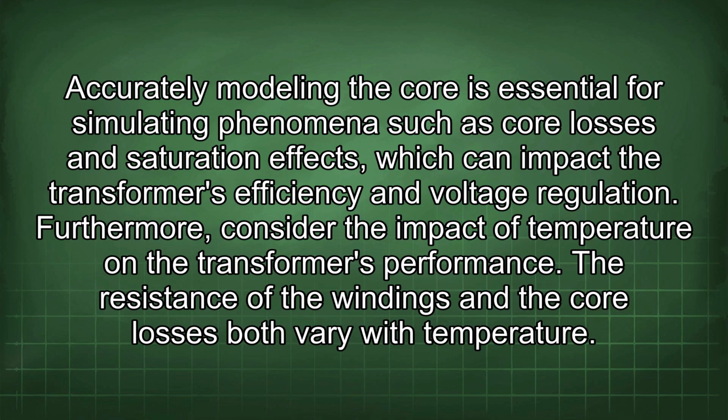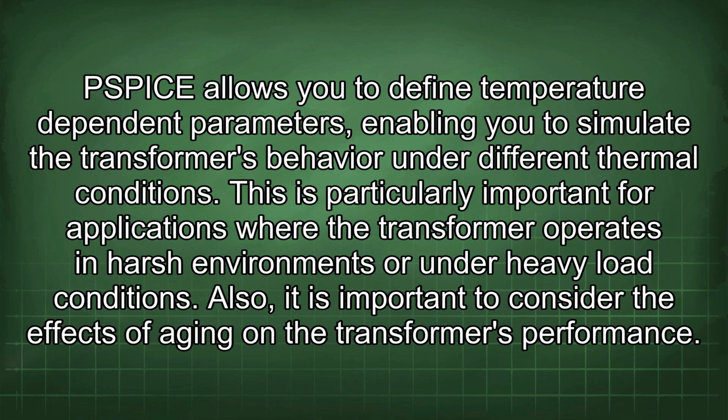Furthermore, consider the impact of temperature on the transformer's performance. The resistance of the windings and the core losses both vary with temperature. PSPICE allows you to define temperature-dependent parameters, enabling you to simulate the transformer's behavior under different thermal conditions. This is particularly important for applications where the transformer operates in harsh environments or under heavy load conditions.